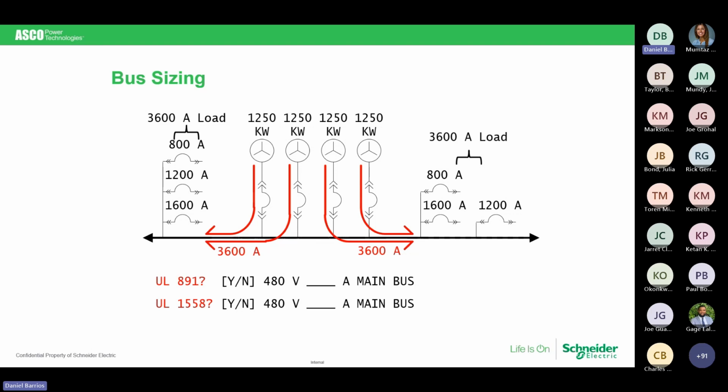Another thing, when you're looking at stacking the breakers, low voltage, the maximum vertical that I can have is a 6,000 amp vertical. I may have an 8,000 or a 10,000 amp bus, but based on the trip units, we'll discuss that with you. I know your frames may exceed that, but if we look specifically at the trip units, we can see how many of the breakers we can stack, because we're relying on no more than 6,000 amps vertically.